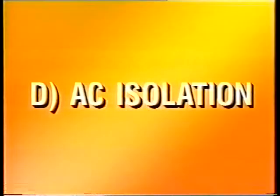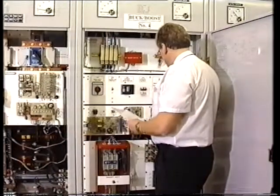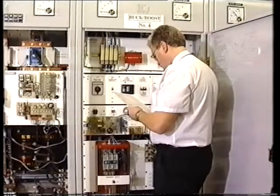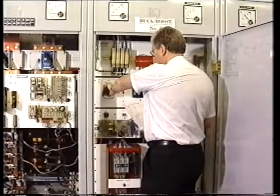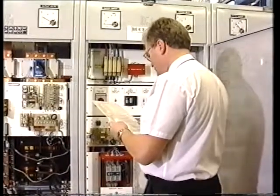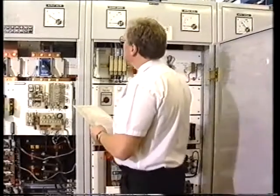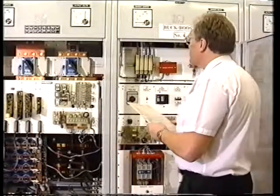Let us begin with D, AC isolation. Looking at the procedure card, if a single buck-boost power supply needs to be AC isolated, then all that is required is to switch off its AC input, and it is recommended that the isolation be carried out at the power supply rather than at an external AC distribution point. This ensures that the correct unit is isolated.